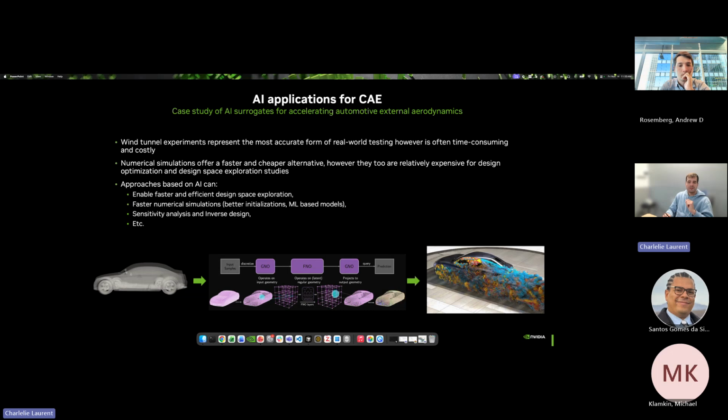And also, something I didn't mention before is that if you run a wind tunnel, let's say you want to do an actual simulation of your car, like an LES simulation or something like this. If you run a wind tunnel, you're going to have some measurements, but there is no way you can use this to inform your simulation, right? If you use a virtual wind tunnel, you get your output velocity fields around the car, and actually you can use those to initialize a new simulation.